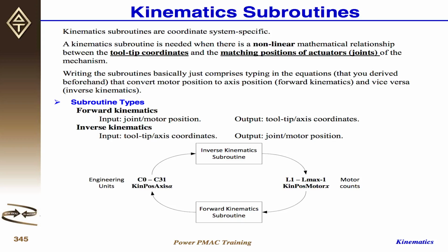So different coordinate systems can have the same axis name, like the x-axis in coordinate system 1 can be different from the x-axis in coordinate system 2. They have to belong to two different motors, okay? And the motion program is actually executed under a coordinate system, meaning the same motion program can be executed in coordinate system 1, and it can be executed in coordinate system 2, as long as all the axes used in the motion program are already defined in that coordinate system, okay?